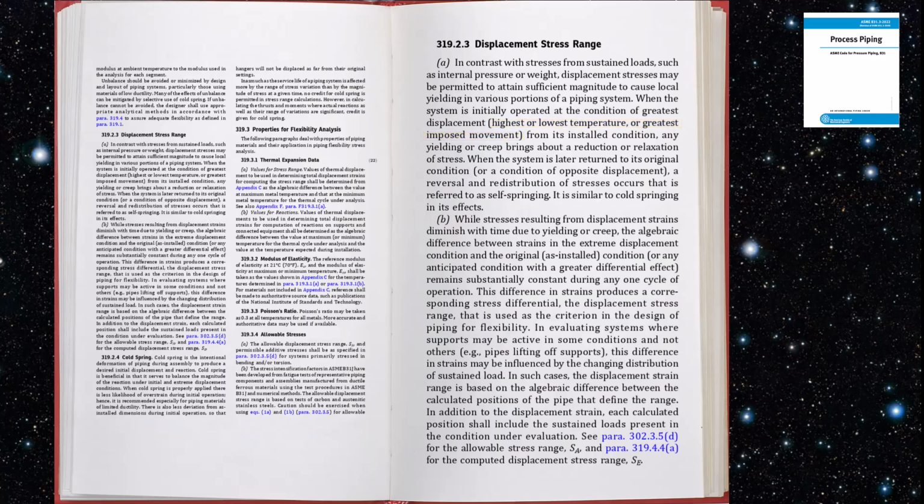Further, this paragraph reinforces our stress-strain diagram study with reference to allowed yielding. Recalling our study on the stress-strain diagram and the cycle and its repeatability, that is further supported here in paragraph 319.2.3 as shown. This repeatability of reversal and redistribution of the cycle ensures a safe design.